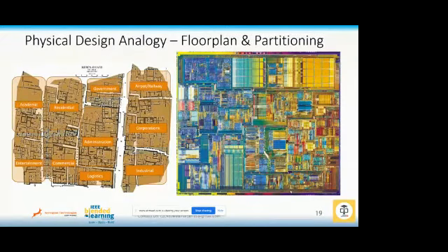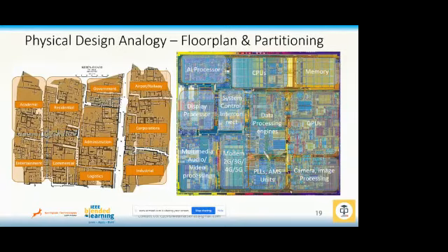Similarly, if you come to an SoC, go to the next one, Hari. If you look at an SoC, I've taken an example of a mobile SoC, which is used for a smartphone. You have multiple GPUs, CPUs, and AI processors. If you look at the latest mobile chips, the AI processor is becoming bigger and bigger. You have display processors, multimedia audio and video processors, a modem, which is the key 2G, 3G, 4G, 5G functionality, and you have data processing engines and PLLs, which are the basic analog mixed signal components.